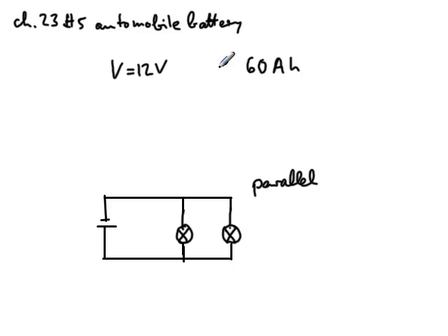So the entire charge of the battery would be this one here, expressed in amp hours. Makes it a little bit easier for the calculation than coulombs itself. And then it says, suppose that you forget to turn the headlights off. If each of the two headlights draws 3 amps, how long will it be before your battery is dead?